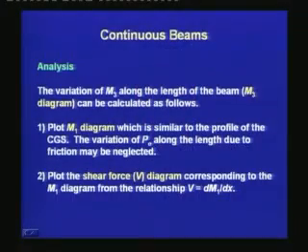The second step is to plot the shear force diagram corresponding to the M1 diagram from the relationship V is equal to dM1 divided by dx. At this stage, we do not know what the reactions due to the prestressing force are. In order to calculate the reactions, we are going through the principles of structural analysis.